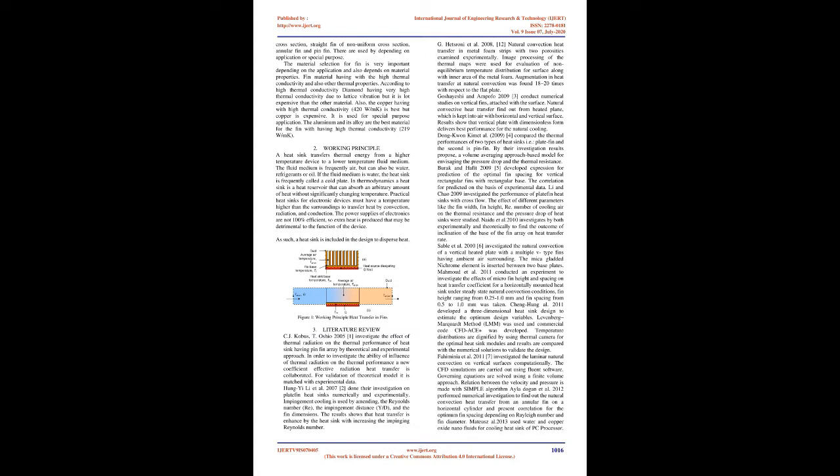Hung-Yi Lee et al. 2007 did their investigation on plate fin heatsinks numerically and experimentally. Impingement cooling is used by varying the Reynolds number, Re, the impingement distance, Y/D, and the fin dimensions. The results show that heat transfer is enhanced by the heatsink with increasing impinging Reynolds number.